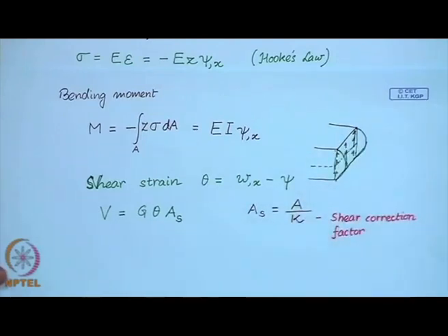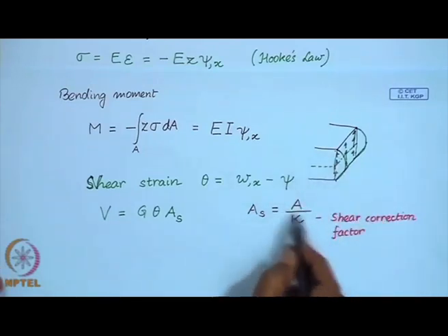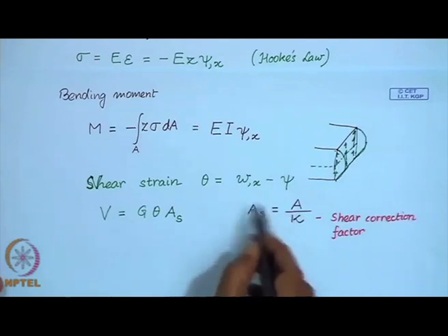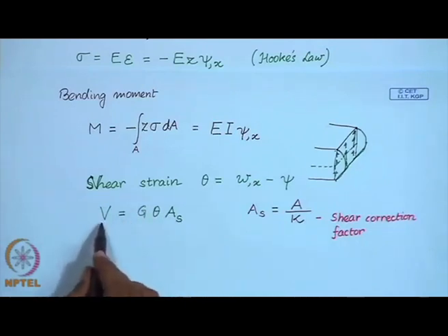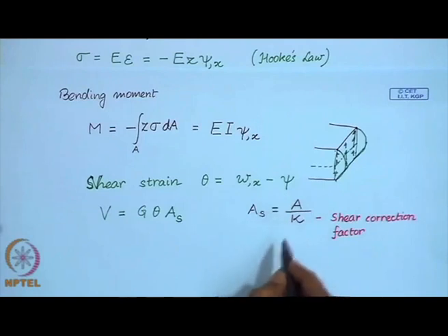Now, to take care of this fact, we introduce the shear correction factor and calculate a reduced area and multiply this area with the shear stress to determine shear force. So, we want to keep the expression of this shear force simple. So, for that reason we have introduced this shear correction factor.